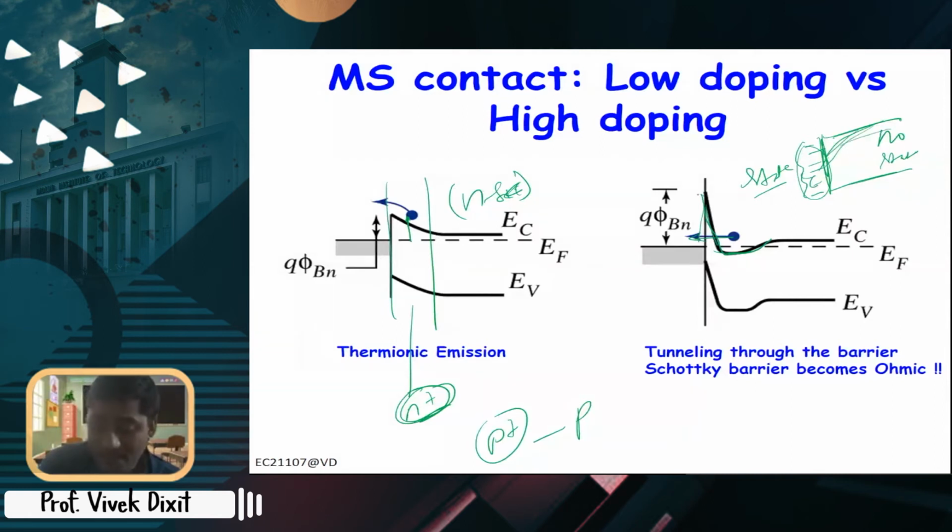So that means when it attaches with the metal, those carriers, instead of being supplied from the bulk energy level, will be interacting with the electrons in the state. Now wherever there are large states, that will be the attaching point for the metal, and there the energy level will lie. And this phenomenon is called Fermi level pinning.